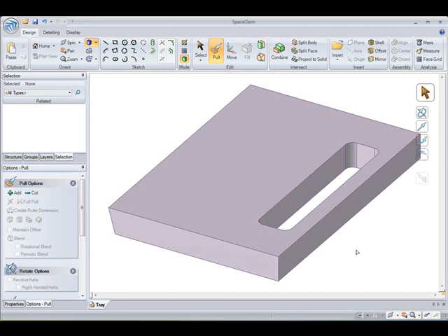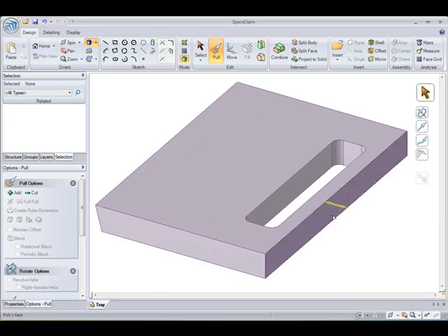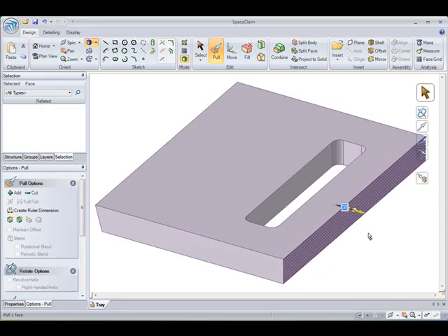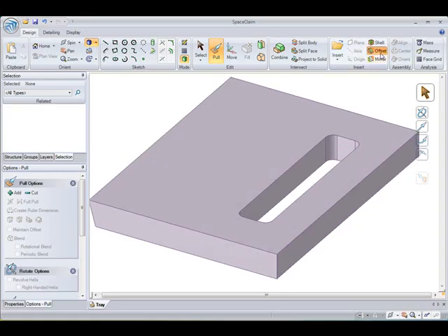Alright, now we'll start adding some more contour to this design to get away from the blockiness of it. But before I do that, I want to add a little bit of distance between our grip and the end wall. So I'll move this out a few millimeters. But now I really want to maintain that relationship I just created.